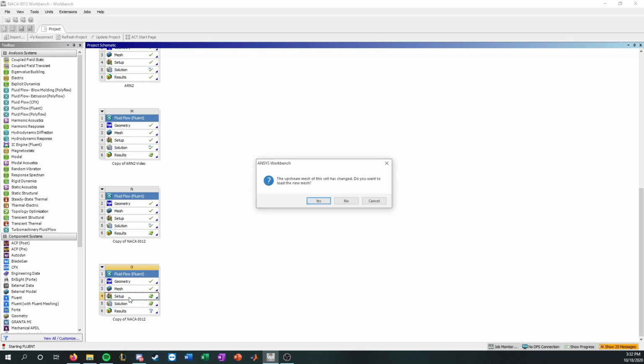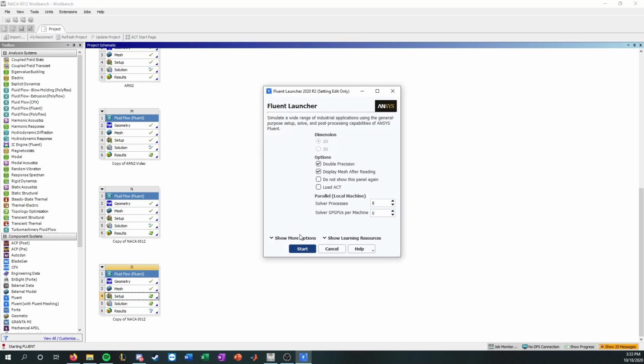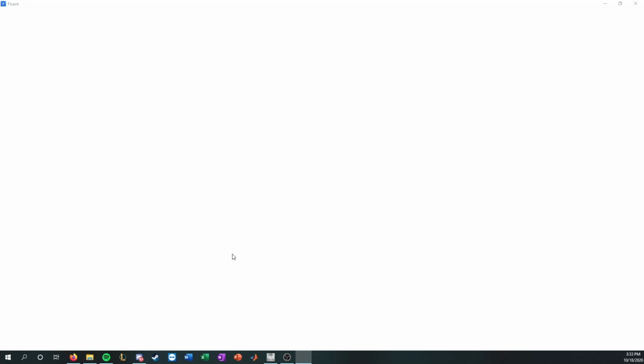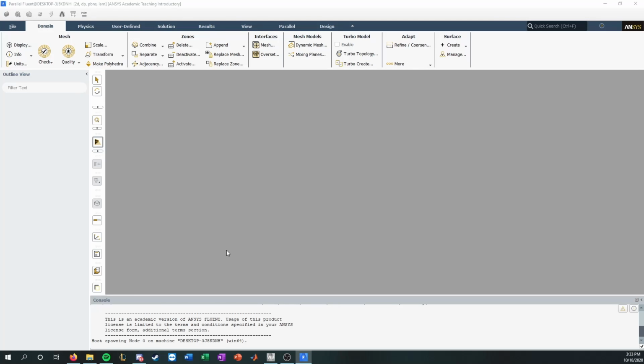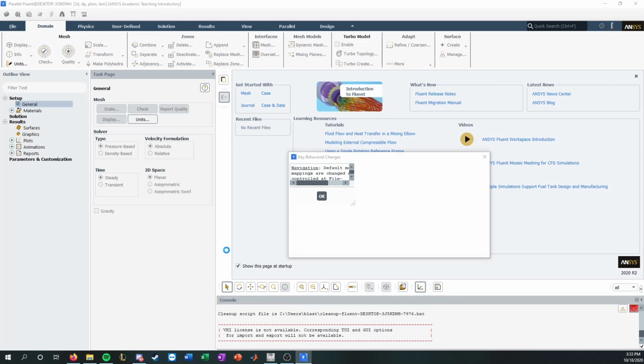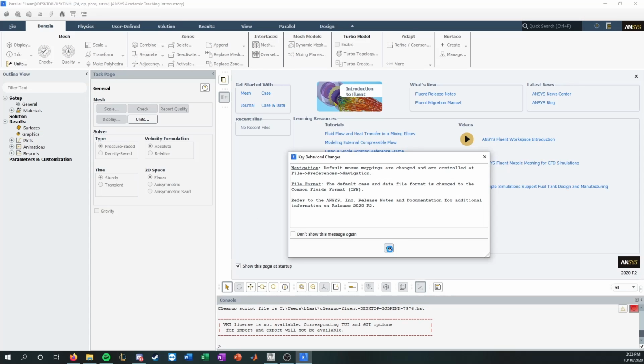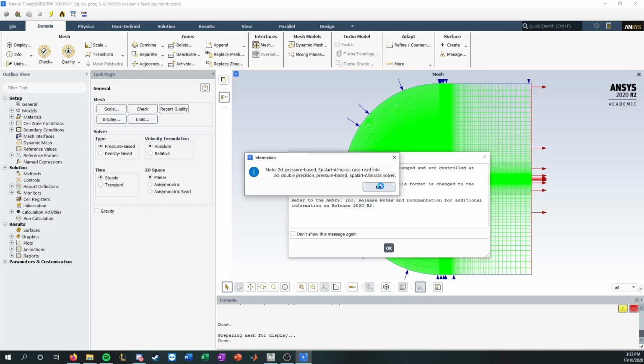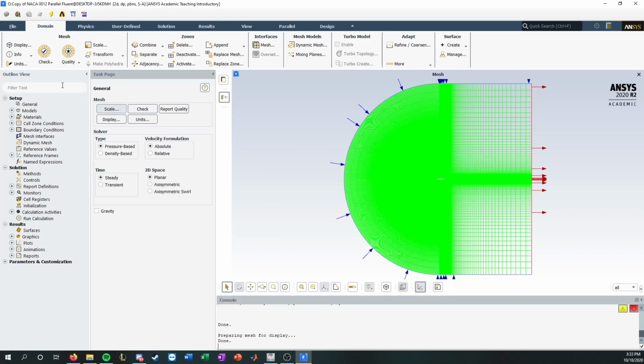Okay, give it a second. Here we go. We have to reload the cells, two-dimensional. And so remember I was saying that vortexes in general are three-dimensional effects. And so what I would expect out of this is to not be able to capture the effects of vortex generators. Instead, I would imagine simple separation. And so there are many aspects in this analysis of why this doesn't work. One is the turbulence modeling. So I guess the two big parts are the assumptions in turbulence modeling,